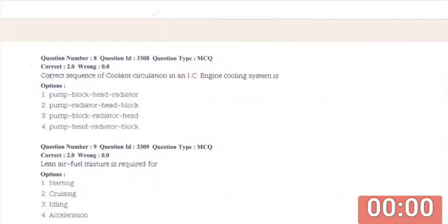During cruising, the mixture is lean as the emission is controlled by using this ratio. Hence, more air is burned for the equal value of fuel when operating at standard sea level. These weaker mixtures give a good economy when compared to the economy of the rich ratio mixture.